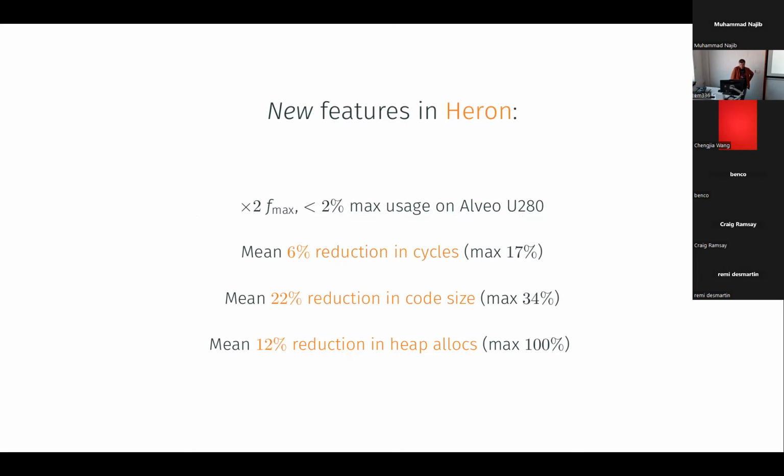So that kind of translates to a few improvements. Just targeting a modern high-end FPGA with some thoughtfulness behind how we map our design onto the new resources, it means we've increased the maximum clock frequency by, well, it's doubled. But the really exciting thing and the low-hanging fruit for us now is what used to only just fit on one of the contemporary FPGAs is now under 2% of quite a high-end FPGA. So the obvious thing for us to do is to explore throwing down lots of these cores and trying to coordinate them in some interesting way.